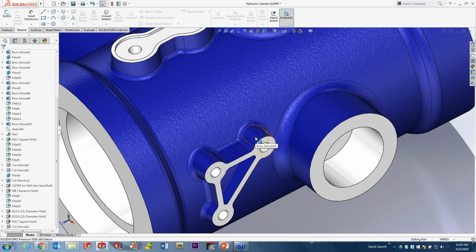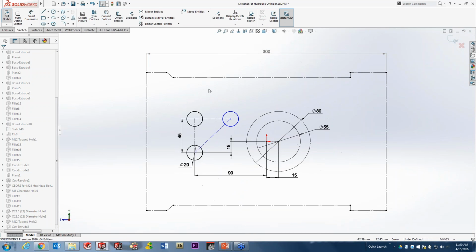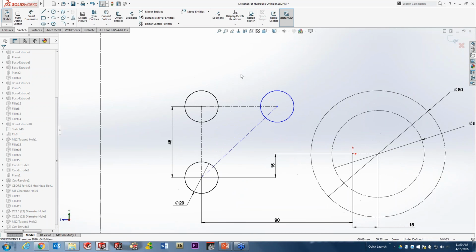Now down here in the front there's a specific issue, and I tried to lay a little groundwork on this one, but most of you really weren't aware that it was happening. When you look at a sketch here, especially with the relations on, we see things like horizontals, verticals, equals, and tangent, and all these great relations. But you've never seen an icon where two lines come together, where their points are coincident with each other. There's no relationship here.